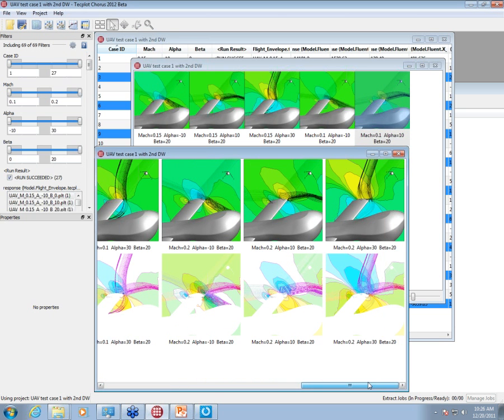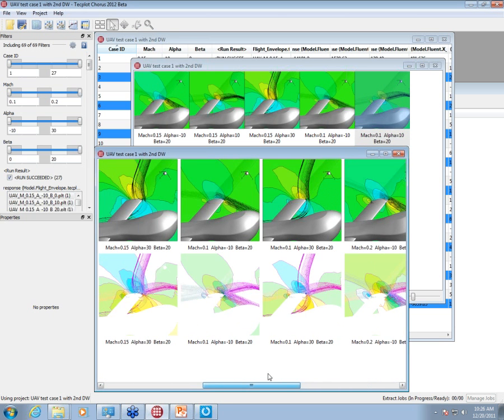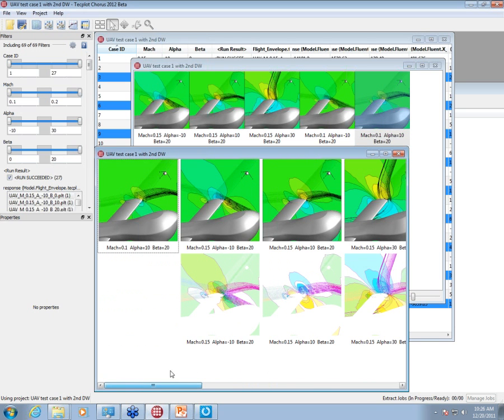The advantage of the pixel difference is that it's very fast. And the second advantage is that it's insensitive to variations in the geometry. It'll show up, but it's a robust difference. Even if the geometry changes substantially, you can do that difference. Which is convenient if you're doing grid sensitivity analysis and you're more of an exploratory CFD practitioner, then you can use this image difference very quickly, even though you can't do a point-by-point difference.